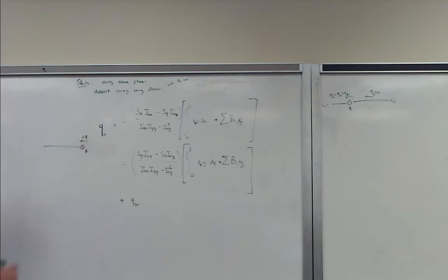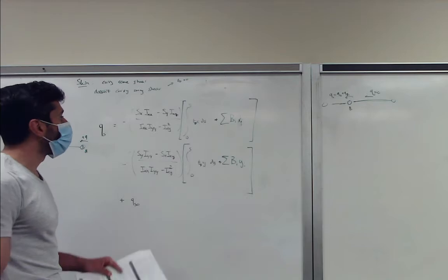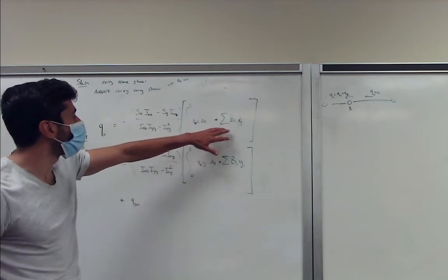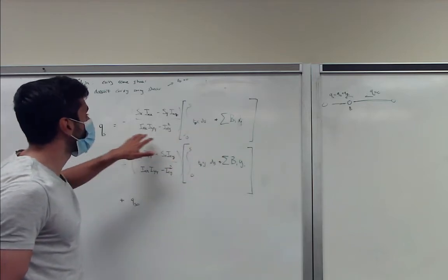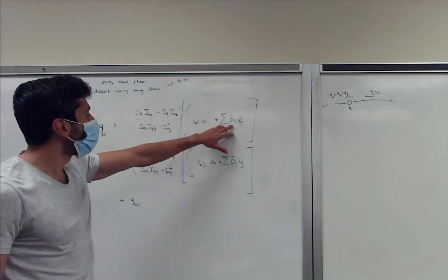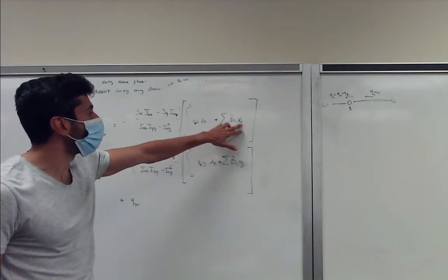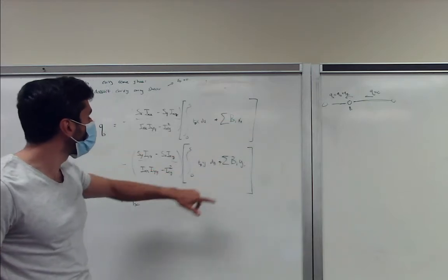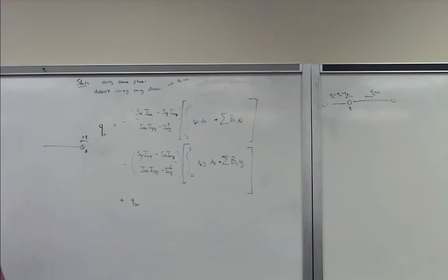So plus some q here, and that's represented by the increase in shear flow being equivalent to the boom area multiplied by the distance x or y, depending on if we have symmetric sections, and xy, Sx and Sy shear forces.